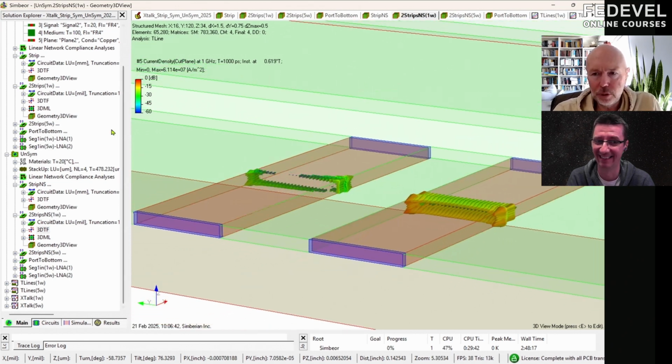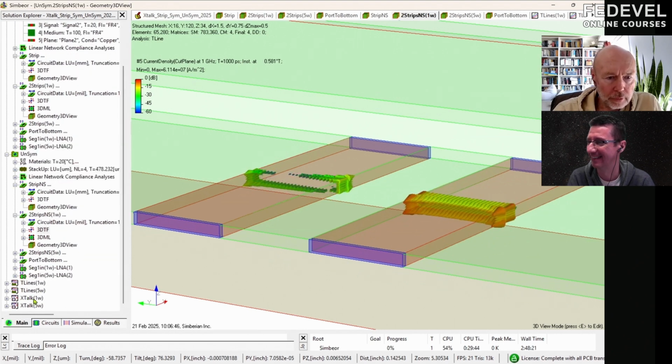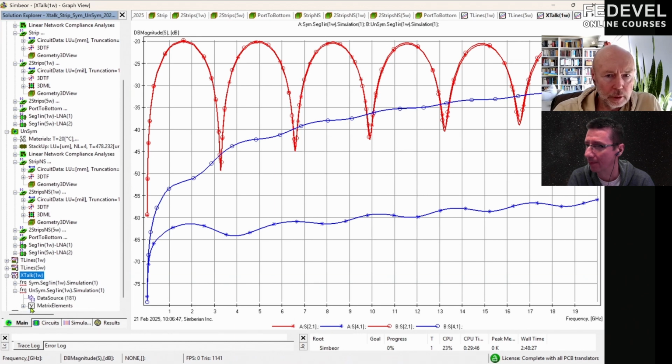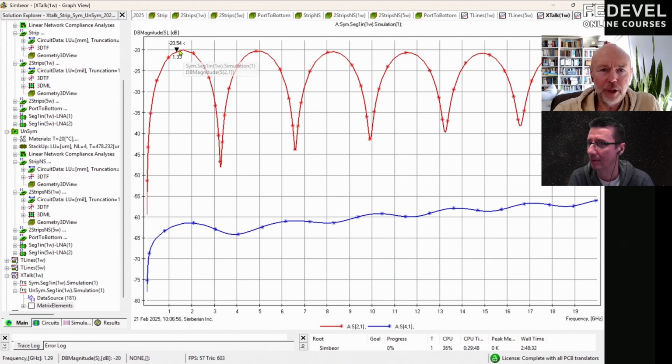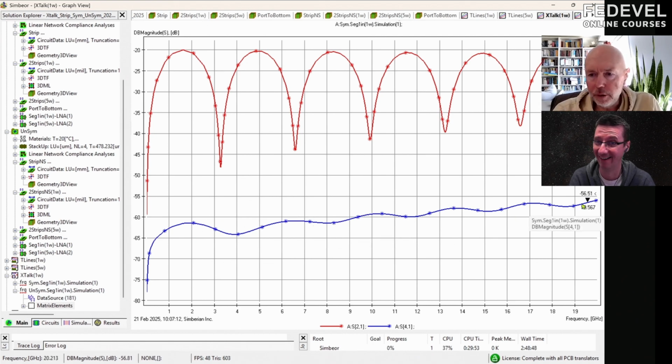What actual the crosstalk, far-end crosstalk and near-end crosstalk in those cases, and I put it on the graph. Crosstalk with 1W, and this is symmetric case, and magically we have -20. Wow. Again, 50 mil near-end crosstalk. And this is symmetric stack up and 1W distance between the tracks. But the blue far-end one is very low. Yeah, it's very low. Yeah, it can be even lower.